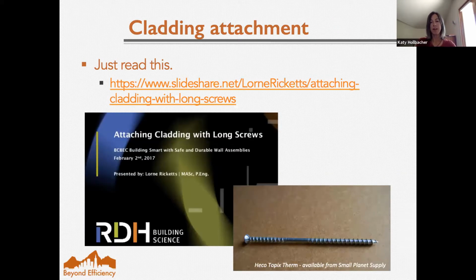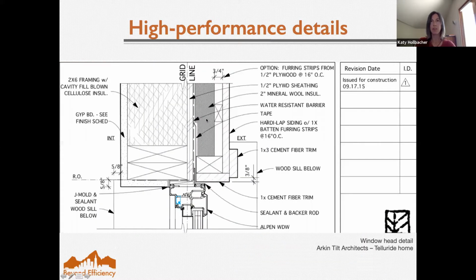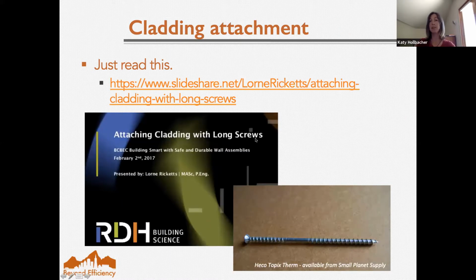There's a lot of concern in a detail like this of, well, how do you attach the mineral wool? How do you attach these furring strips? How can you be sure you're hitting the studs when you go through? People are concerned about mineral wool compressing and the siding deflecting. In reality, the service loads, even from fairly heavy cladding, are very low in relation to the whole system. And rather than getting more into that, which could be a 2-hour talk in itself, you'll see this link again in the slides that we'll follow up with.